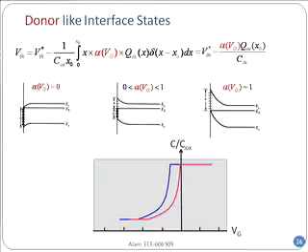A little bit more, if I now try to invert the substrate, all the defects are up above the Fermi level, everybody is positive, a huge change in the threshold voltage. So I will have the final curve over there. The first curve was supposed to be magenta and the last one is red. Hopefully you can see that.